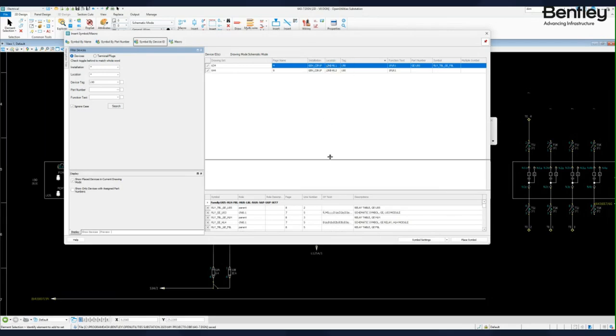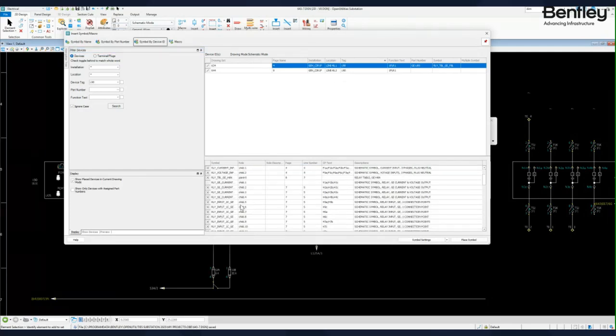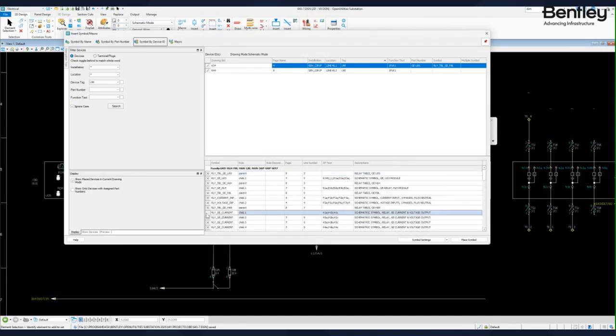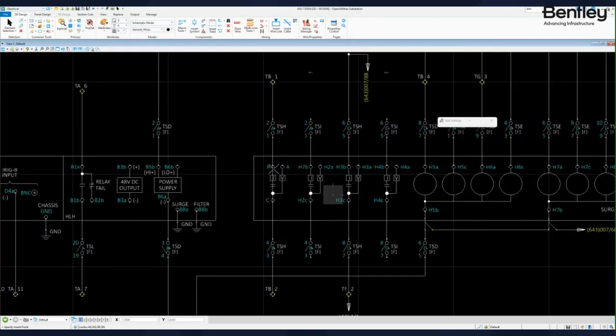And here, as I can see for my L90, I have different symbols representing the different functions of this device. Pretty much every single symbol is already placed because I have the information here. Now I can simply click on one that is not placed, my child one, which will be our schematic for the current and voltage output, and place the symbol somewhere here, aligning with this.